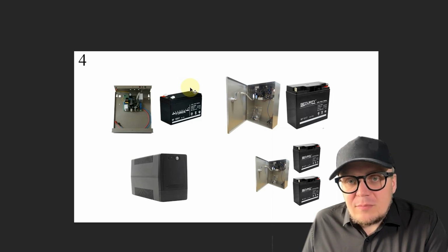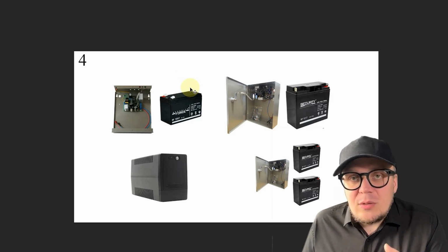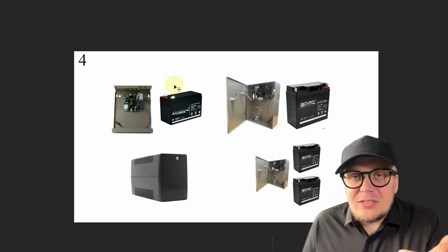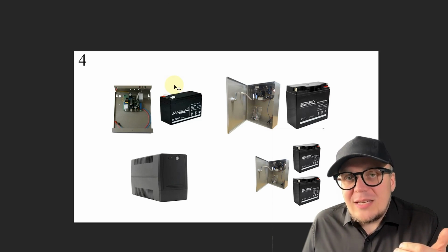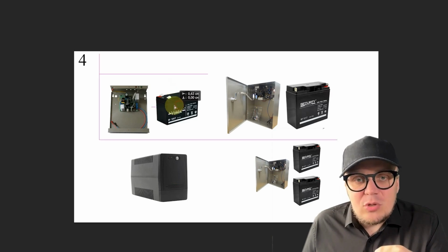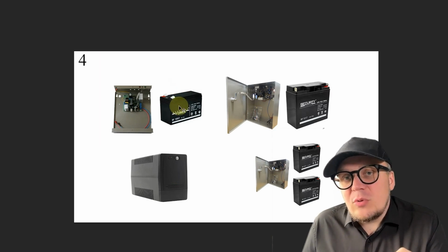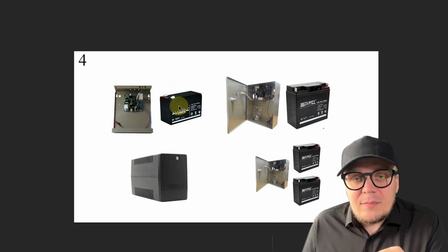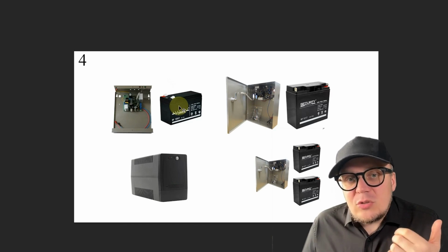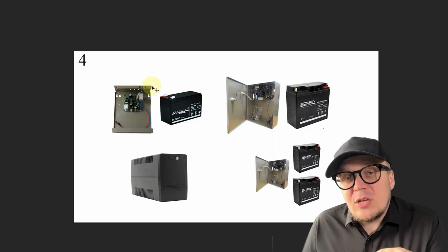Well, regarding the installation of an uninterruptible power supply, any surveillance specialist will tell you. And if you have already received some consultation, then you have already been informed that this is a basic necessity that is absolutely required. Because surveillance systems are low voltage systems. HD is always 12 volts, IP is always 48 or 52 volts if we are talking about professional equipment. And low voltage surveillance systems are very susceptible to damage during thunderstorms because voltage fluctuations occur during storms. It is necessary to install an uninterruptible power supply with a voltage fluctuation protection option.